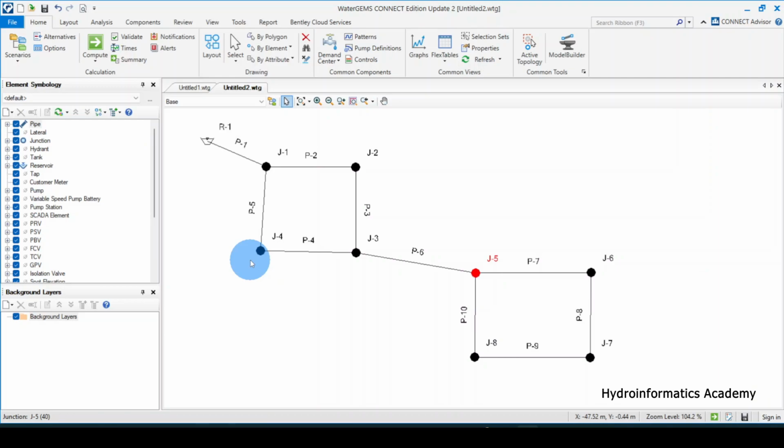Okay, so we don't need to go and enter properties one by one. So you just click at junction 1, junction 2, junction 3 and enter the values, just like what we did in the previous tutorial. By using a Flextable, our life becomes even much easier. Okay, let me show you how to use the Flextable.